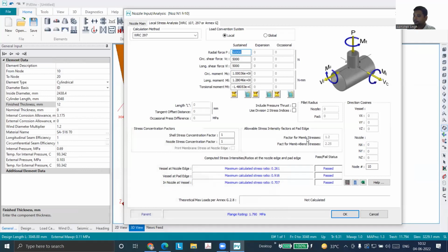First, we shall go with the stiffener because the long weld neck will be costly. Unless the client demands it, the fabricator will not provide it because they cannot accept any cost increase. If the client is insisting, then you are bound to do that. Actually, I saw these gussets in a different scenario, in lateral, kind of inclined agitators where the drive is mounted on the nozzle. Correct.